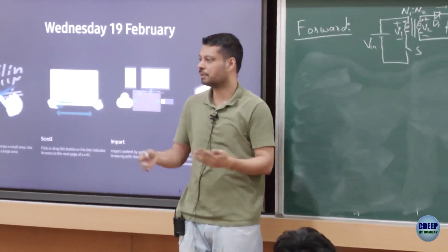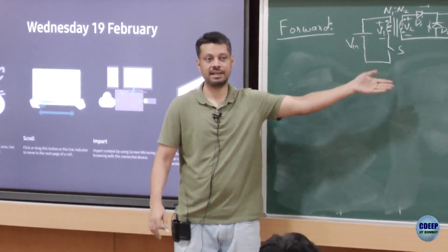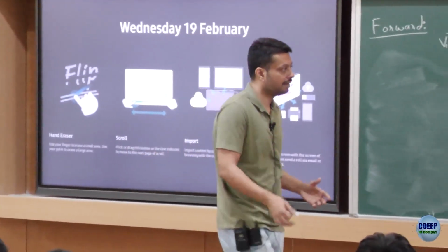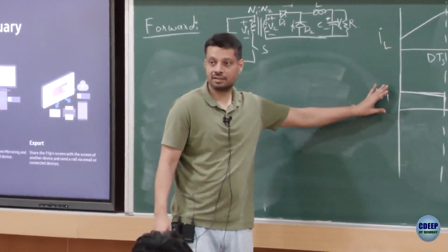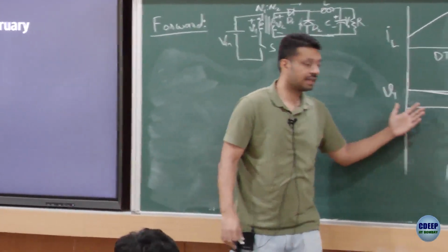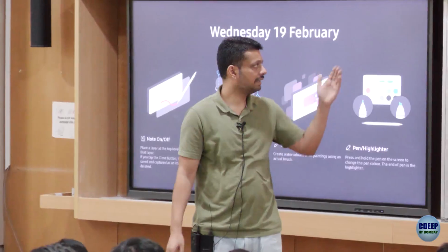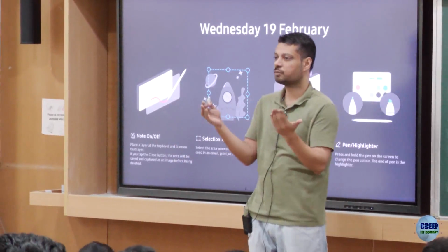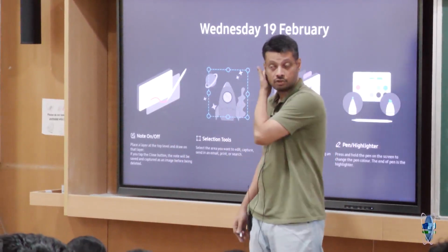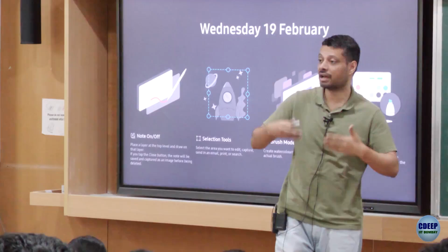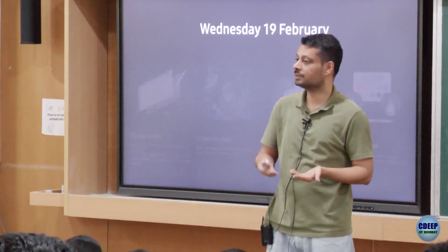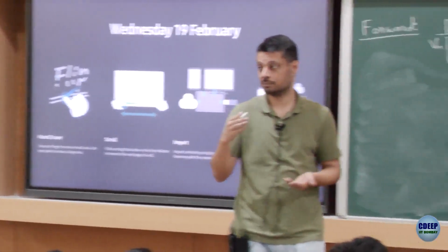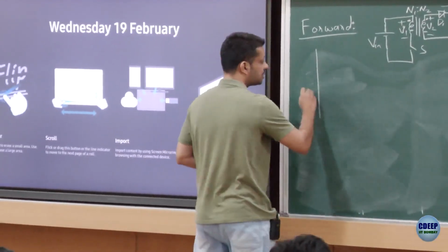In circuit simulation it may work because it's some ideal transformer. In reality this circuit would never work. Is that okay? We have to figure out a way of making this voltage have some negative component so that the average is 0. In this case the V1 voltage is plus and 0. Average is positive, right? Average is not 0. So if you apply a positive average voltage to a transformer, the flux will just keep on rising, right? And current will also keep on rising exponentially because you remember the BH curve, na?